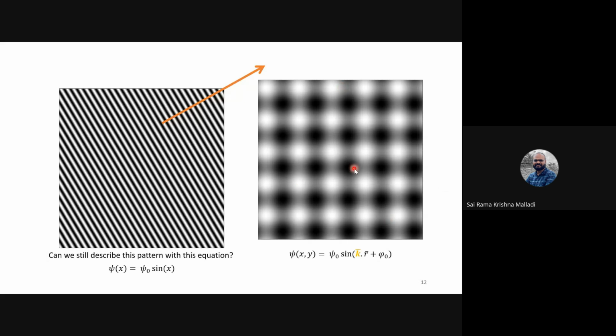Now, when I look at what is called a high resolution TEM micrograph, if I imagine atomic columns sitting like this, and an electron wave interacts with periodically spaced columns, the distribution of atoms oriented along a particular crystallographic orientation appears as an interference pattern that you see here.